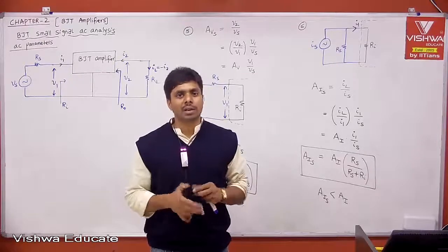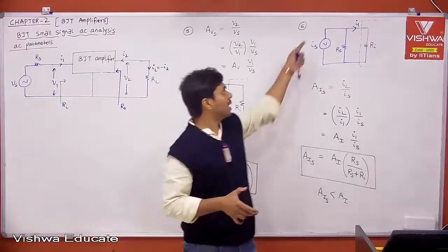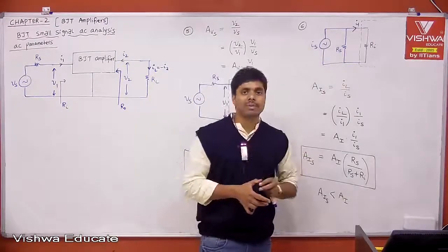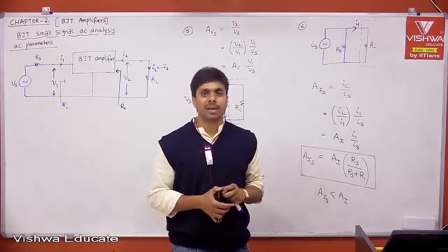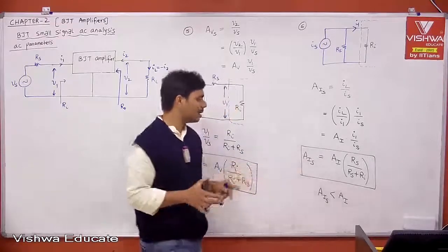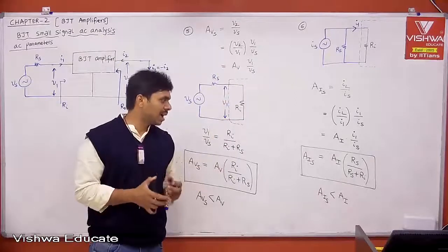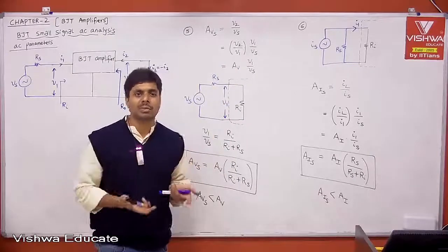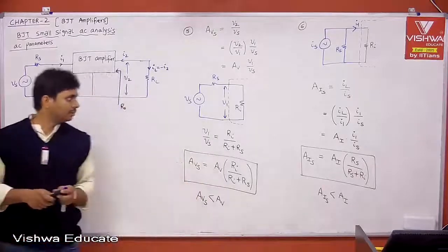Theoretically we can say, if Rs is infinity for your current source, then you'll get only IS, and the IS will enter into your amplifier, then we can get the maximum current gain you can get from your amplifier. But that is not practical, okay? Therefore, whatever may be, the real current gain including source resistance is less than the available gain, less than the maximum current gain, okay? Take this.